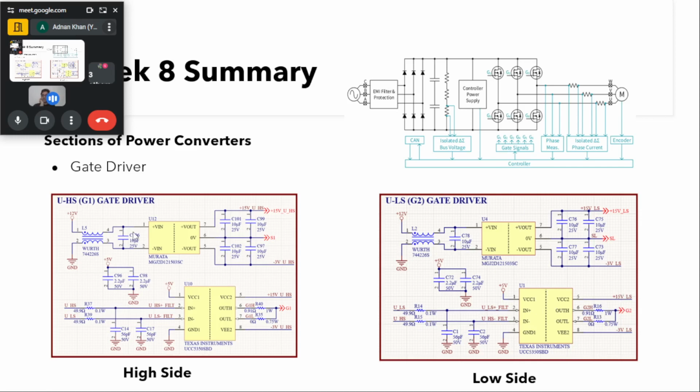But for the high side switches, as we had discussed earlier, the sources of these devices will be having a floating supply, and the sources of these three legs won't be at a common potential.